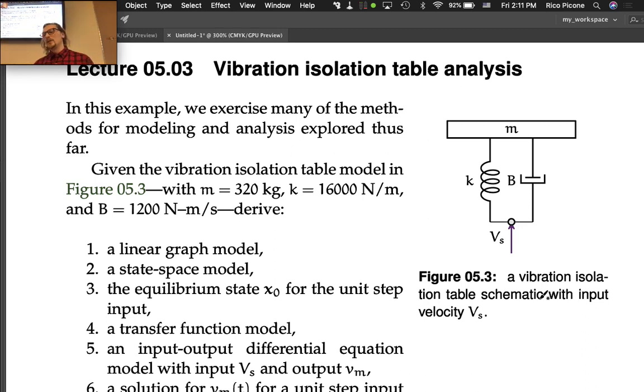Say you have a motor that's on some chassis, and almost inevitably you're going to have a bunch of vibrations coming from the motor, or if it's an engine, you have even more vibrations coming from that. A lot of times those vibrations can cause issues in other equipment. If your engine or motor is bolted to something that's stiff, it'll transmit these acoustic waves through your plant or your room or whatever it is you have it in.